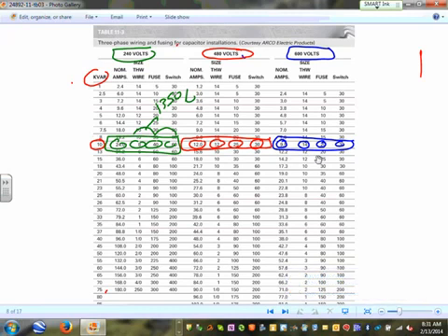Yeah, good. For one of the ones I asked, it said that 1 horsepower is equivalent to 746 volts or watts. But a 1 horsepower, 200 volt single phase motor, according to table 10.2, has a current of 9.2 amps, and they want you to explain the discrepancy. The full load, yeah, because of the watts. When you have a motor, the watts are what make the motor work. The full load current in the table is typically for safety, so they add a little bit on it.